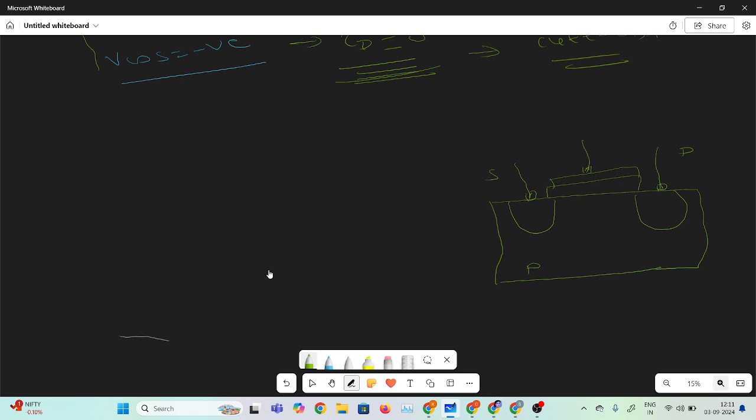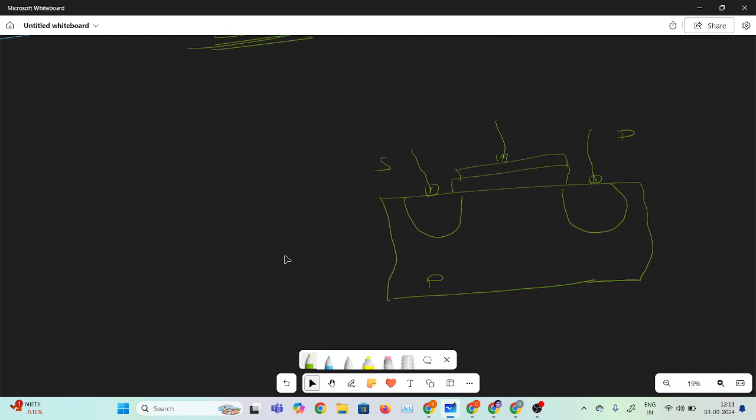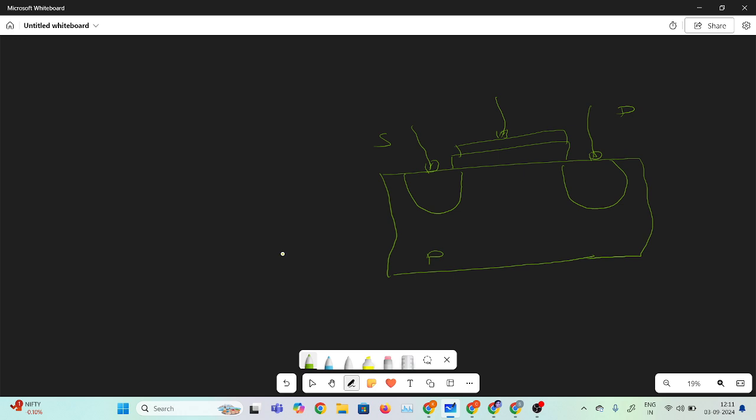Now, how the construction is in the case of the n-channel enhancement MOSFET: this is the p-type substrate. Now we will apply a positive voltage. If we apply a positive voltage on the gate terminal, this is positive, and the channel is non-conductive in nature. Inside there are holes, this is the p-type representation, and the minority electrons are there. In a p-type semiconductor, electrons are the minority.